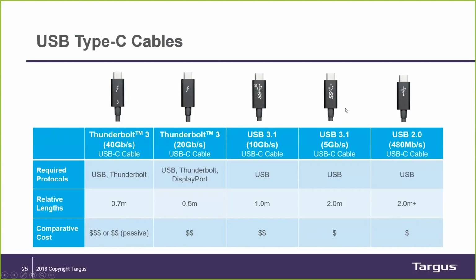That is to say, if you're using just USB for USB docking or dongles, make sure it has the SuperSpeed logo. If you need the faster speed for alternate mode or USB SuperSpeed Plus, look for that little 10. And if you're using Thunderbolt, make sure, especially if you're using 40, that you have the little 3 there. So cables are important also.